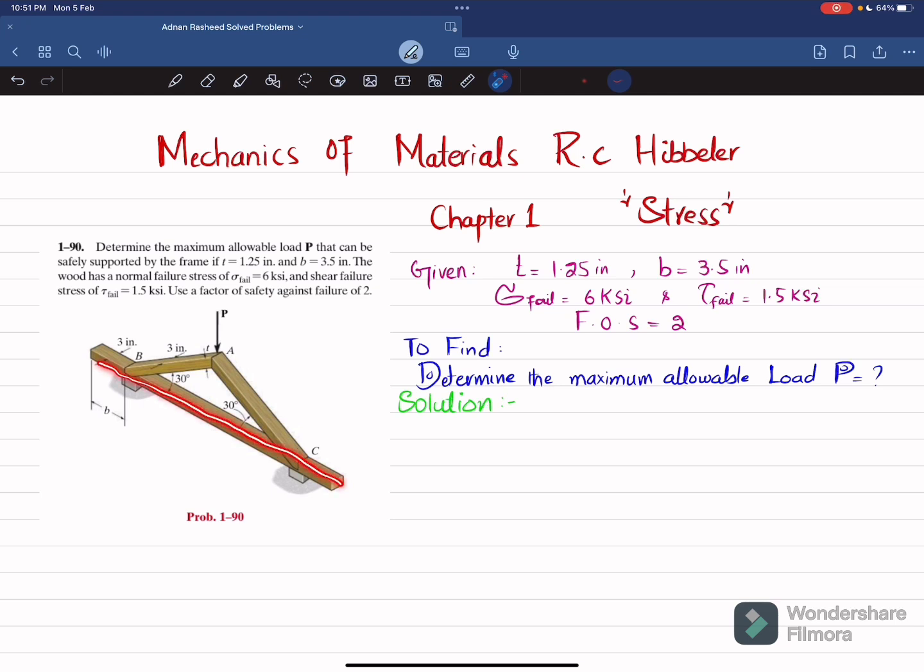So you can see this is the frame, clear, that is acted upon by load P. The thickness T is given as 1.25 inch and this B is given as 3.5 inch. And the normal failure stress is 6 ksi and the shear failure stress is 1.5 ksi. So you have to find this P load for the factor of safety of 2. So let's start with the solution.